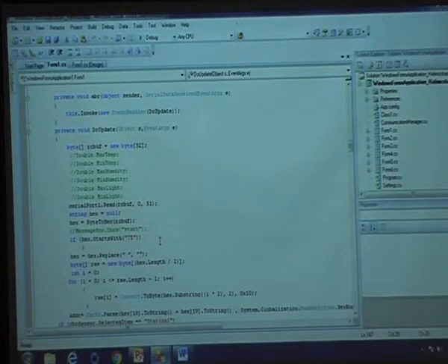There is another program which shows the escape sequence also being taken care of, but this program will let you understand how to extract the bytes from that particular frame. So here the starting byte is nothing but 7E. If the starting byte is 7E, obviously it indicates that it is a frame starter for me. So the condition is if x starts with 7E, then what you need to do here.